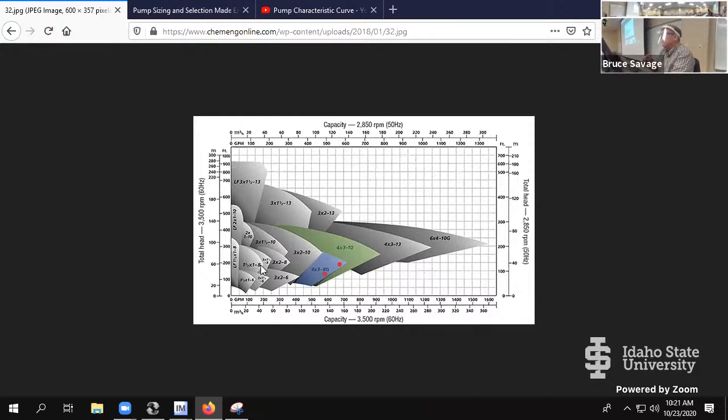They don't know your system. They'll give you the one point that you think is the best, but understanding the whole system and how it fits, and why, if you vary a little bit in your flow rate or your head, one of the other pumps may be better. So you might want to look at 3 or 4 right in here, plot the pump curve and verify that you have the best one. Okay. All right. So given that information now, let's go back and learn another piece of information.